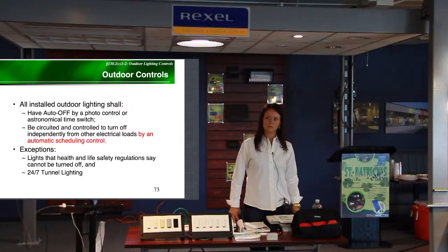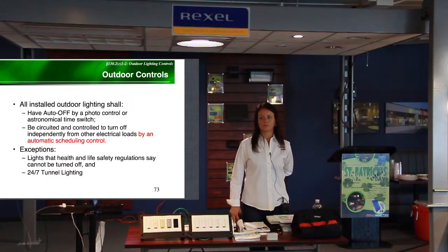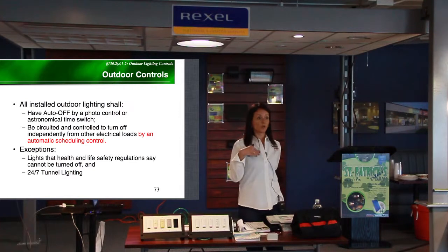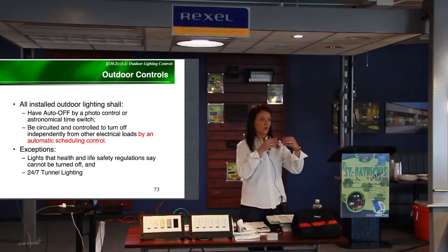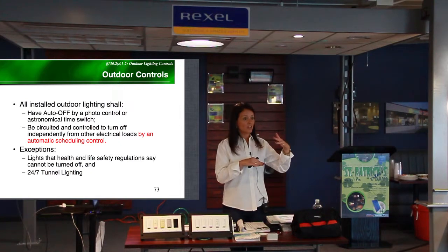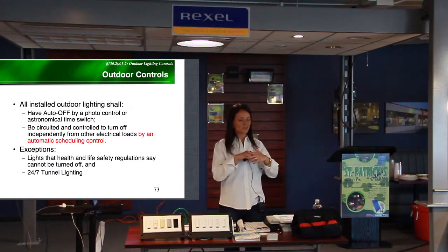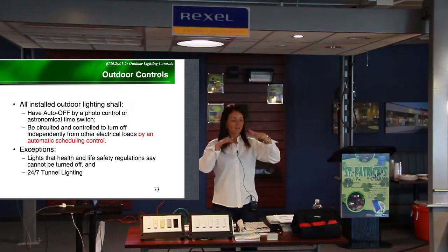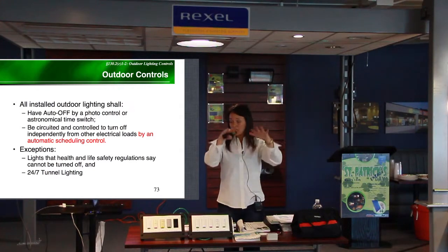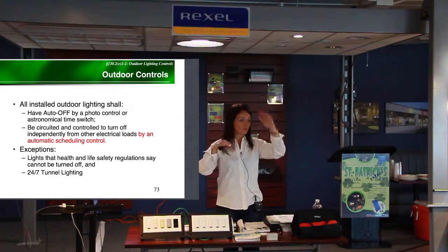Right now, and just very simply, because we're going to have a whole separate class in a future time about outdoor lighting, there are ways to get around that with dimming to certain levels also, because of the codes in the city of San Diego and the county of San Diego. Depending on the municipality, what I'm seeing as a manufacturer working with a lot of outdoor exterior LED lighting manufacturers to use our sensors, high-low is becoming way more common. And then the low level with LED is very efficient. And as long as you maintain, again, fixture-based control, so you have your uniformity levels, you can cut by, I don't know, 80%, and go down to 20%.